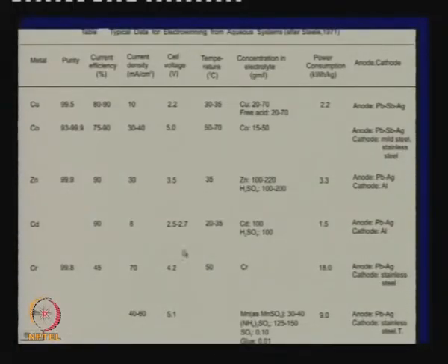Yet, the metal you produce really is not required at that purity for most applications. The most important application is galvanizing, which will do with a lower purity, but we can't help it. We have to put pure zinc. In some cases like copper, we settle for a slightly lower purity, but it has to go for electrorefining later on, because we want to recover the precious metals.